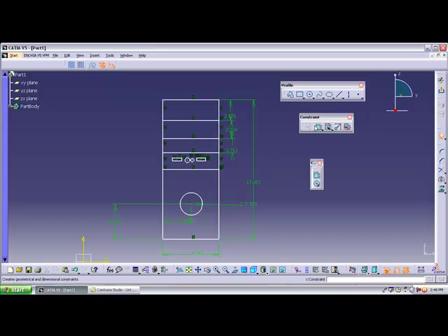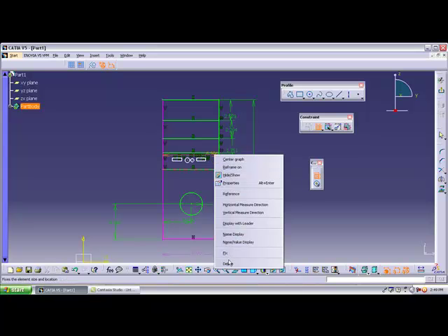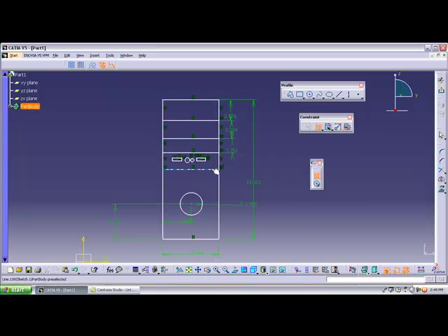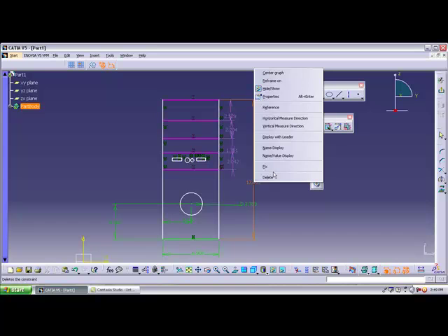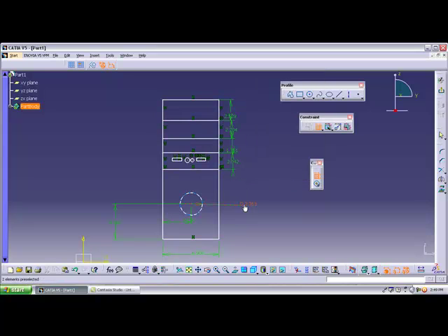So when we give this dimension, what should we do? If we give this dimension, what will happen? We should remove any one of these 2 dimensions. If I select these 2 lines and give dimensions, see here, these objects are only colored in pink color. These are not appearing in pink color. It means we should remove any dimension between this. Suppose if I remove this one, it can remove this dimension. Right click and delete.